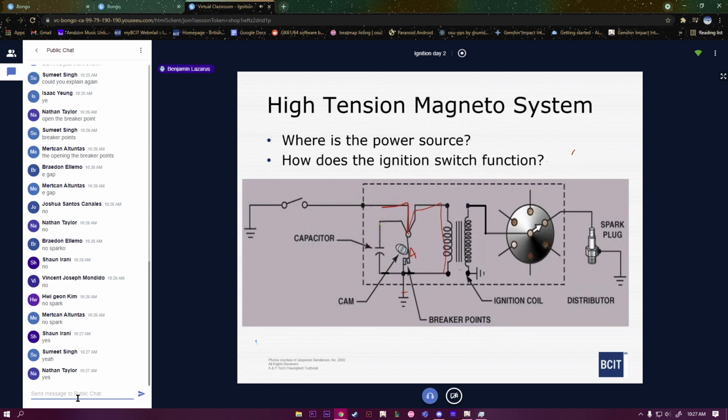Well, what's this? This is path B, just drawn differently. If I close that switch, then opening my breaker points doesn't do anything, because my electricity goes in either this circle or this circle. It looks longer to you and me, but it really isn't any longer for the electricity. It doesn't care. So the closed position basically grounds out my breaker points and renders them useless.